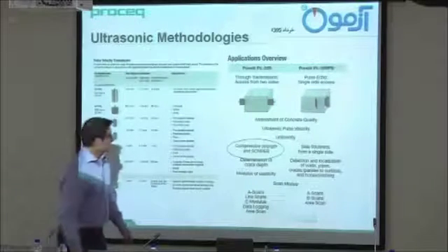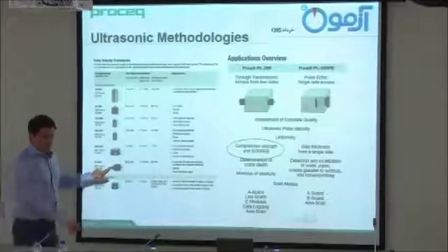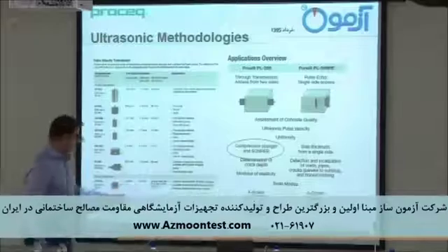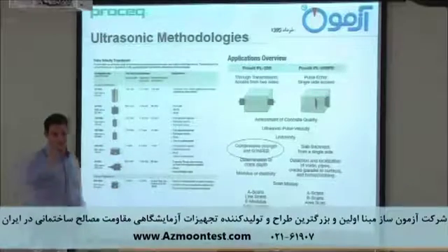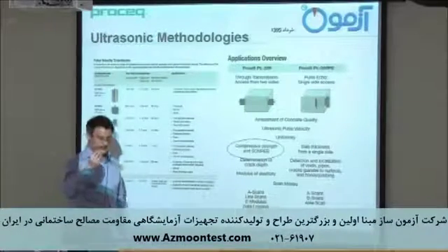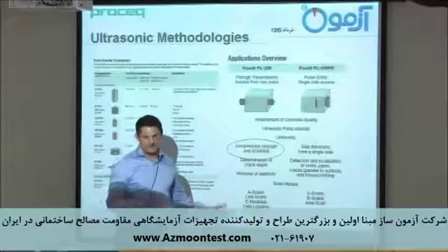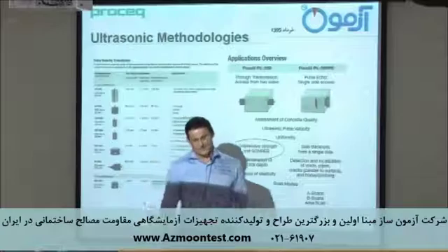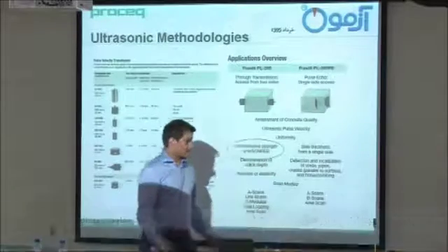Okay. So this one and the pulse echo work without couplant, the rest is with couplant. And for shear waves, it's a brown couplant, not the same. It's very sticky, but very useful to get the E-modulus. It's sticky and it's better to use. You have better contact. Okay?